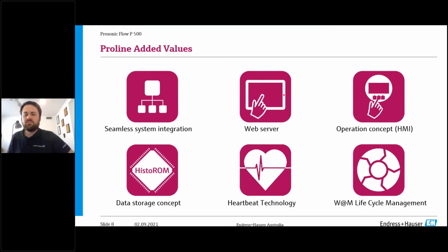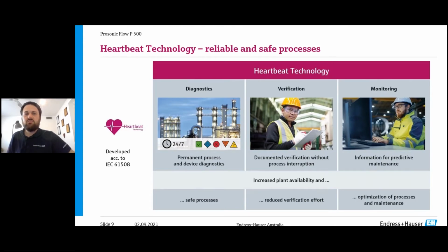We have Heartbeat Technology, and our life cycle management capability as well is available. Now, on Heartbeat Technology, I know a lot of you are probably already familiar around this concept around diagnostics, verification, and monitoring. For those that aren't familiar, it has been developed in accordance with IEC 61508 so that you can have a traceable verification of the meter if your process requires it or if your operation requires it. And the diagnostics and monitoring enable you to incorporate a preventative maintenance regime into your instrumentation.